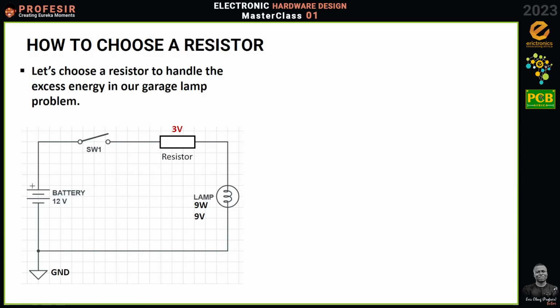Now you see, physically, the bigger the wattage, as we have said, the bigger the resistor. This is because if the resistor is big, it provides a larger surface area to radiate the heat, right? So by using a 6 watt or a 5 watt instead of 3 watts as calculated, I help my system to stay cooler, okay?